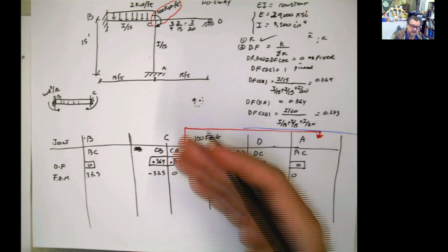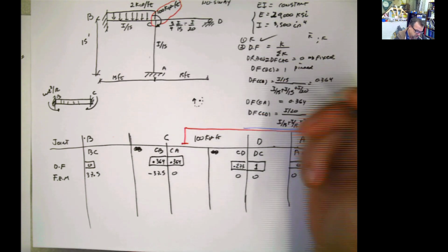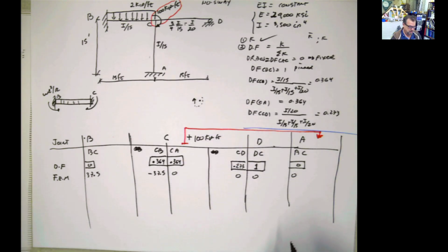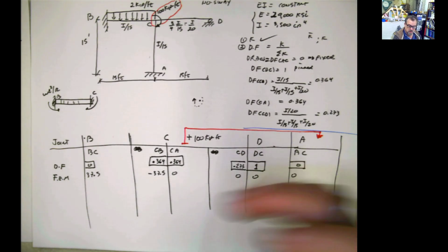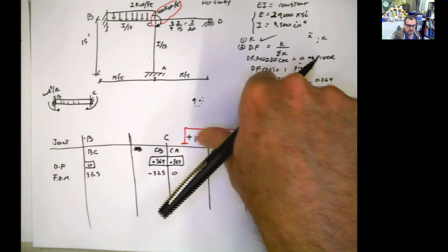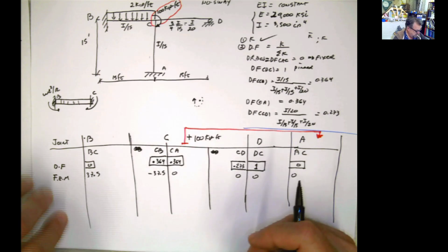I already explained that in the other part. Even though it's clockwise, because it's external, it is a positive moment that is applied there, not a negative moment. For the internal ones, we are using the convention counterclockwise positive, clockwise negative, but in this case, because it's external, the convention gets inverted.